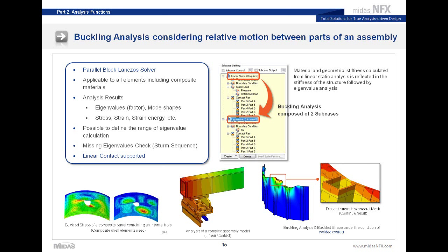The buckling analysis also can be done, and what is interesting to note is that you can use a subcase to perform first a linear analysis and then see the results of a buckling analysis on the deformed shape. Because as you know, the loads deform the structures, and the model characteristics of your model can change after the application of the load. So this is why this function is needed.